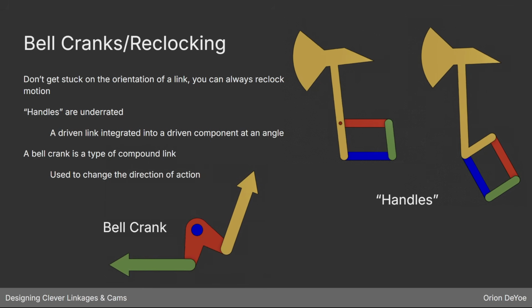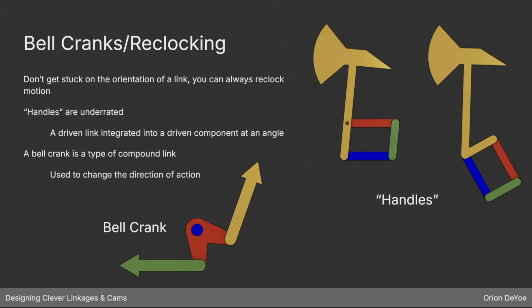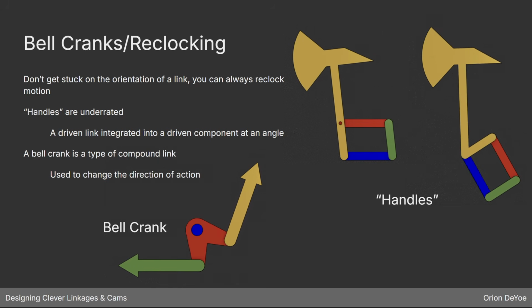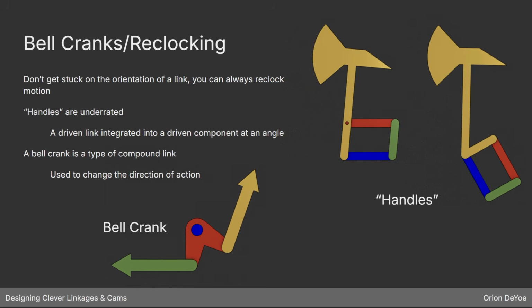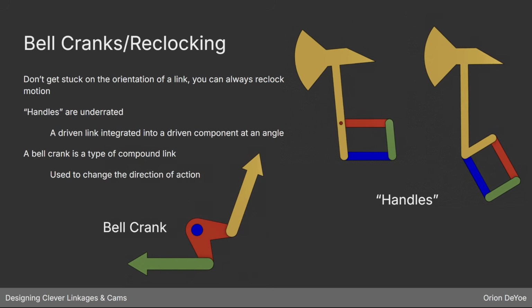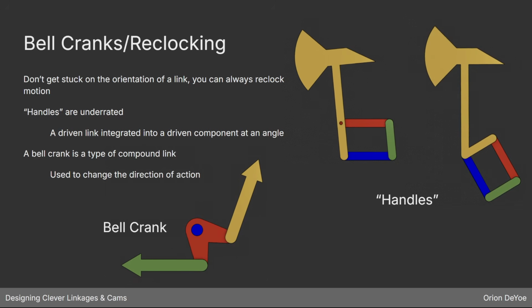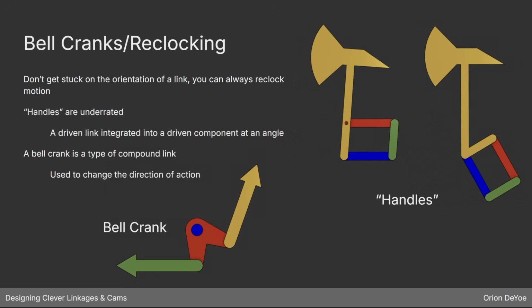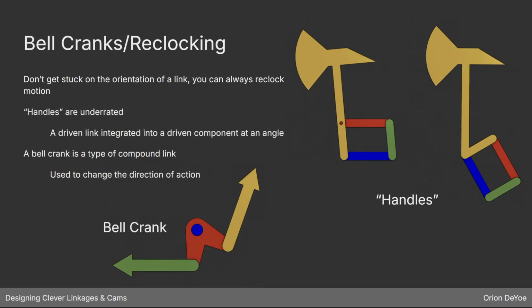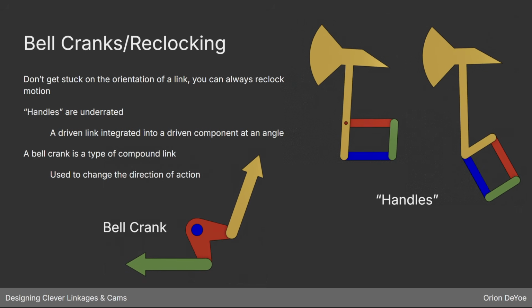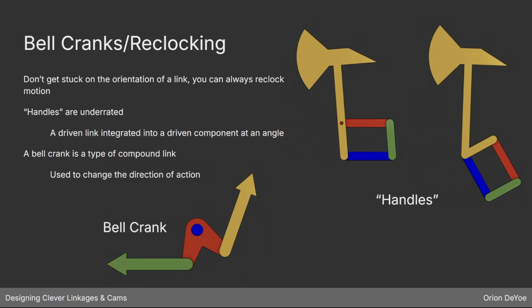I have this thing that there's not really a good term for, but I call them handles, which is this, when you're looking at this yellow part here over on the right, I can take this linkage that's driving this mechanism, and I can reclock it in any orientation by just adding this little lever on the end of the mechanism.